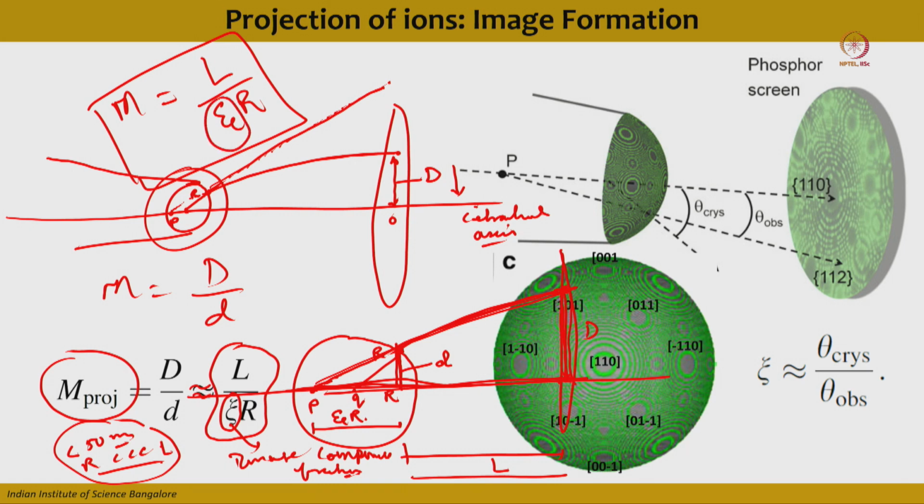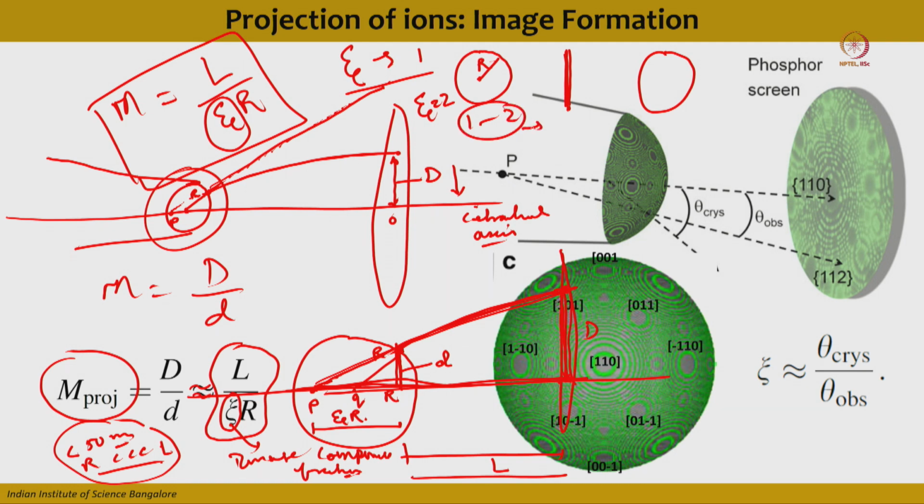So now there are two extreme cases here. Phi can be either 1, which ideally means the tip surface is a sphere because your r is constant, or it is very near to the tip surface. Or the second extreme is phi equals 2, which means 2r, the total diameter, a flat surface. So it should be either a flat surface extreme or a sphere. The phi value is always between 1 and 2. Usually we put it as 1.5 to 1.6 as per the geometry. Fine. So how to calculate this phi?